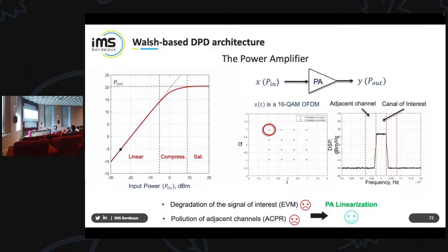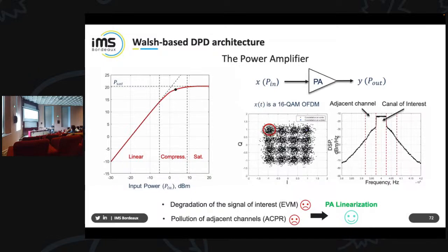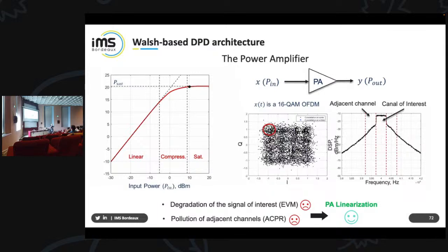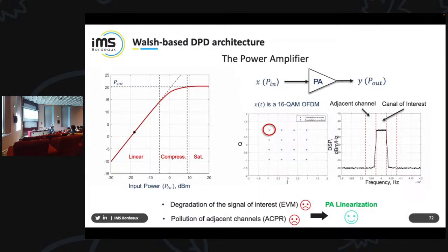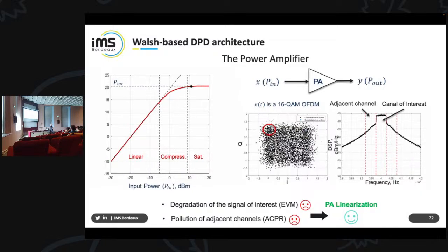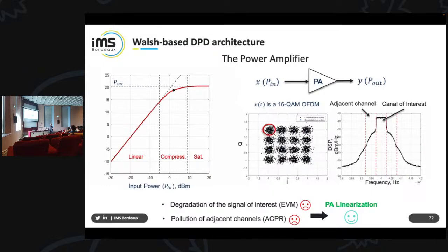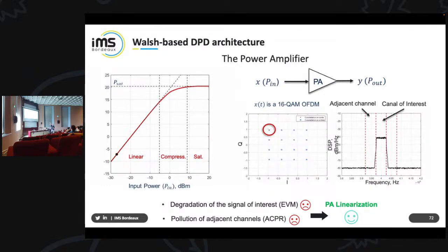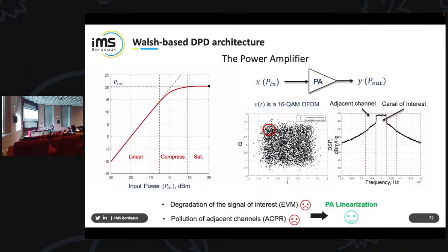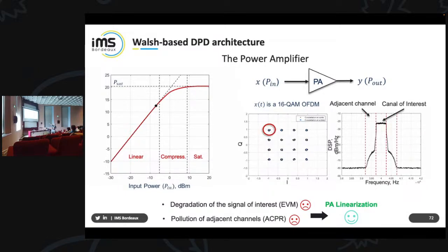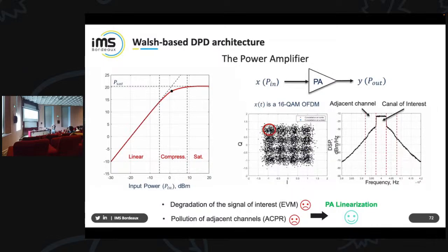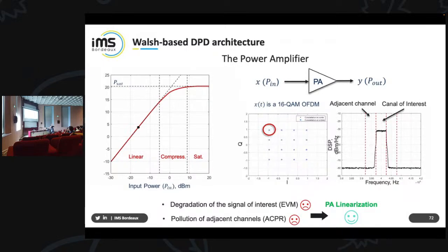And this is what you are going to measure by yourself Friday morning with Maxon. Maxon has developed the whole structure to linearize what we call the power amplifier. Power amplifier, you remember that circuit, common emitter in bipolar or common source, you know, minus GM, RC, whatever, or RD. It's how we amplify a signal. The transistor is used to amplify, but it's non-linear. Here, what you have on the left, the power amplifier will bring more and more power, but at arriving at a given power level, it doesn't amplify anymore. This is what we call the compression point. It will make a saturation.